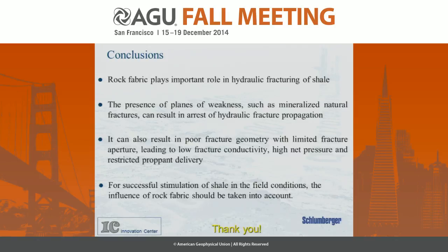And it means that high viscosity fluid allows us to deliver proppants, and it also increases our chances to cross interfaces. We have a higher chance of crossing interfaces with the high viscosity fluid and successful proppant delivery. And in case of water injections, very often the fracture turned, like I demonstrated in the epoxy test, parallel to the pre-existing bedding planes, and produced no proppant delivery.